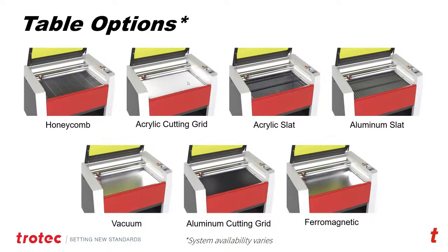And so if you're doing small details, the honeycomb is ideal. If you're doing a lot of acrylic lettering and you don't want reflection, say lighted signage where light is going to go through the acrylic, maybe the acrylic cutting grid, because it'll keep any reflection points from happening. We also have an acrylic slat, an aluminum slat. Vacuum tables for holding thin materials that tend to want to warp and not want to stay flat. So the vacuum table is ideal for that.